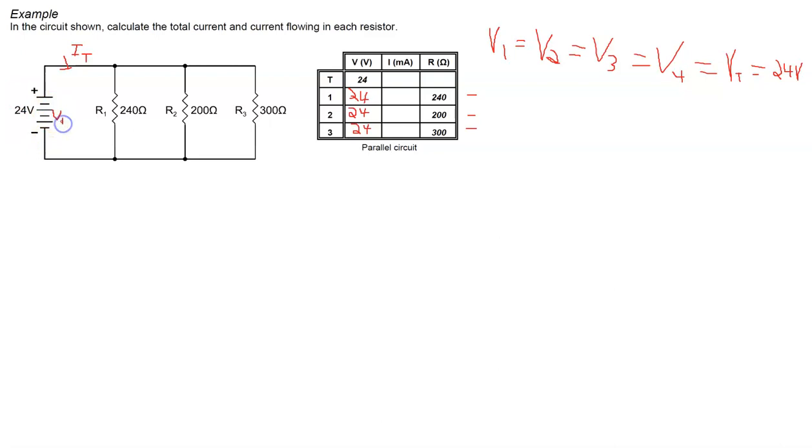And so the idea is that we have 2 approaches to the solution of this circuit, and it doesn't matter which one we take. And so think about the fact that we don't need to start off with an RT calculation for this one. Now that's what I'm going to do, but we could take the approach of find I1, I2, and I3 and then find IT and then do RT last. So RT first, RT last, right? Either one will do. Now I'm going to start off again by, like I said, finding RT.